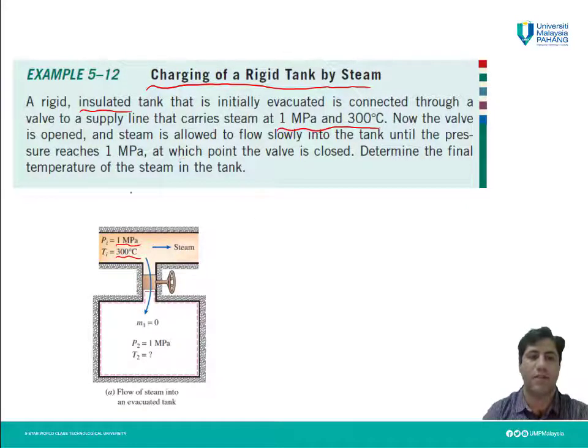This process will continue until the pressure of the steam inside the tank also reaches 1 megapascal. And after that, because the pressure inside the tank is equal to the pressure of the line, we don't have any mass transfer from this line to the tank.